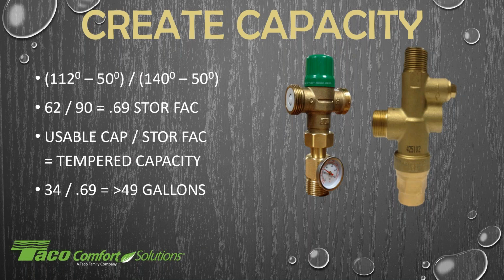Actually, I'm sorry, before I finish that story, I don't think anybody questioned it just yet, but I'm sure quite a few of you out there looked at the 112-degree delivery. And why did I use 112 instead of, say, 120, which a lot of systems are sent out to, or 115? The reason I chose 112 for this formula is because of the storage temperature set at 140 degrees for my tank. A lot of mixing valves out there, and you have to pay attention to the valve that you're using in the project.